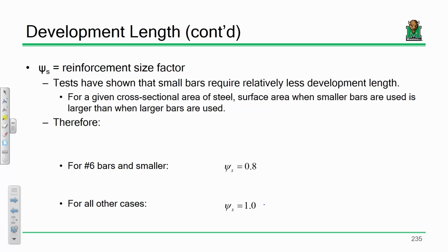I guess, but I'll say this. Normally, in those types of situations, not only are you using epoxy-coated bars, but you are providing more than enough cover to where that probably wouldn't happen. You end up having oversized elements anyways. Like if you're using epoxy-coated bars, you're probably using like 6 inches of cover, 4.5 inches of cover. You got these mammoth reinforced concrete elements that aren't going to have a problem anyways. That sound good? All right.